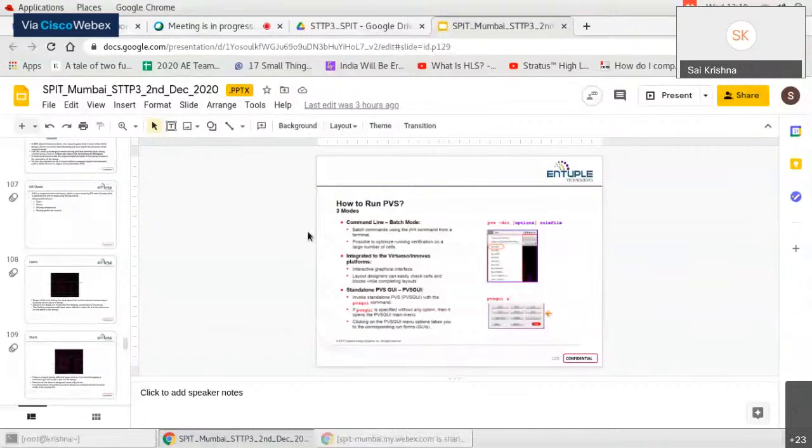And after that, once that is done, you will then proceed with placement. So placement runs first in global placement stage, where a trial run is done, and then based on the connectivity, a detailed routing is done. So here you have to check for your congestion, timing, area, and power. After that, if there are any violations, you optimize your design once, which is your pre-CTS optimization, and then again check for congestion, timing, area, power.